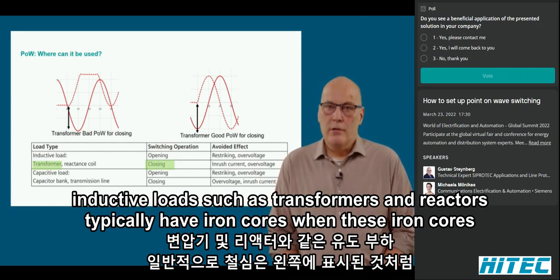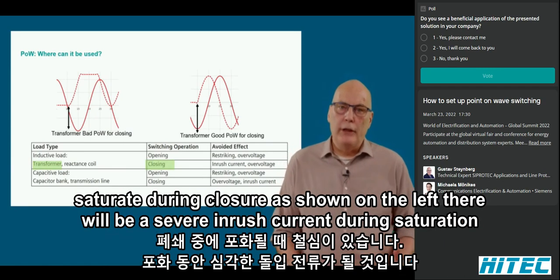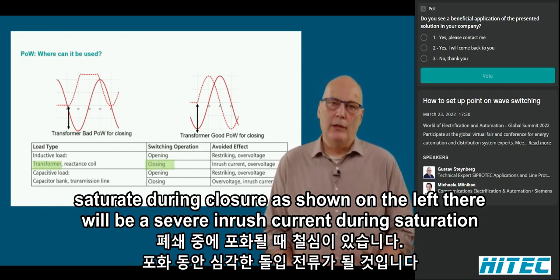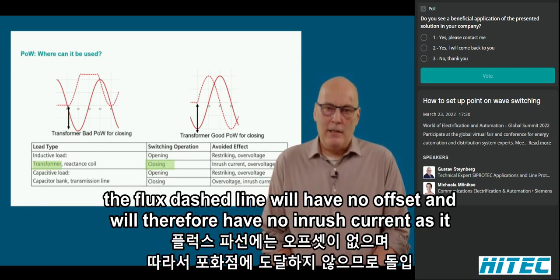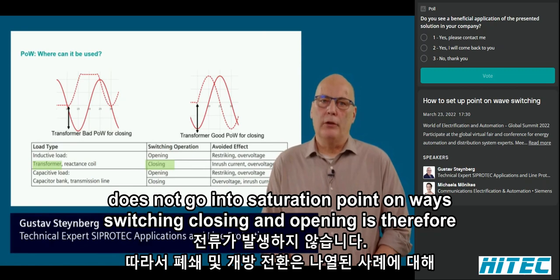Inductive loads, such as transformers and reactors, typically have iron cores. When these iron cores saturate during closure, as shown on the left, there will be a severe inrush current during saturation. If the inductive load is closed by point-on-wave, as shown on the right-hand side, the flux dashed line will have no offset and will therefore have no inrush current, as it does not go into saturation.